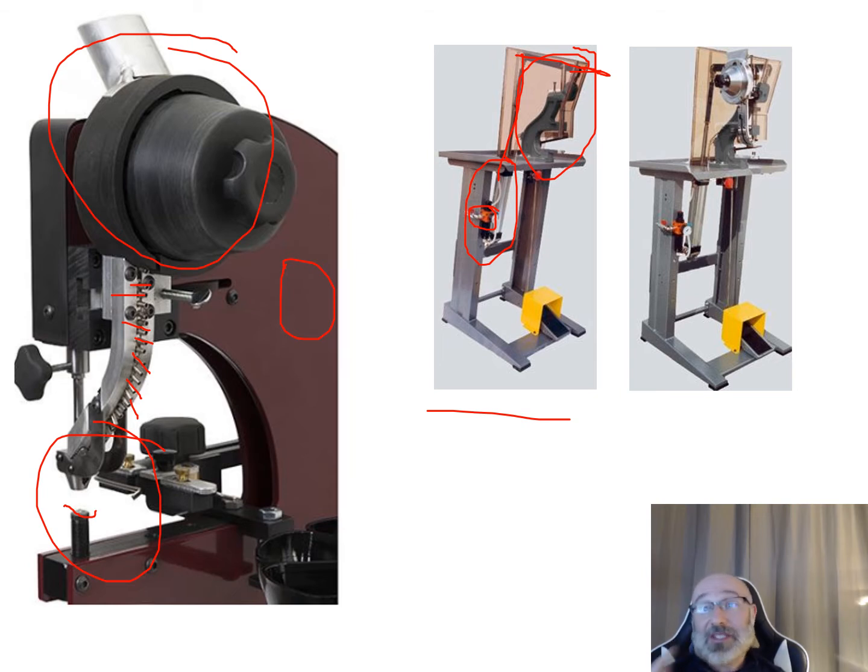So it's a very skilled set that you need in order to achieve the right pressure, the right forces, to get things just right, not to damage the material, and to get the rivets to the right spot where they might want to roll over. So what we can do here, and the beauty of this is when you have this pressure regulator, once you've set it, you can kind of set it and forget it. You say, okay, I know I'm going to need 75 PSI every single time. I hook up my air compressor to this right here, set the regulator to 75 for whatever material I'm working with, and go ahead with just a light touch of this.